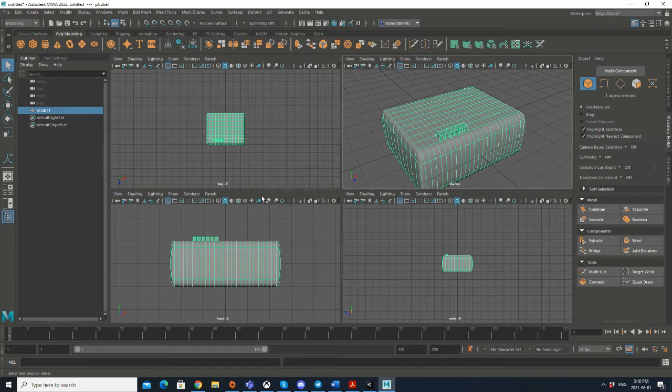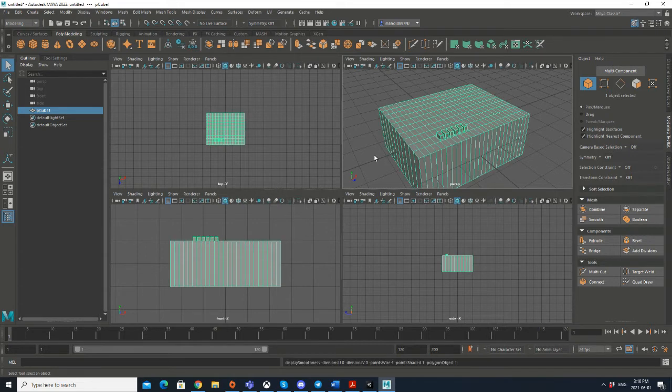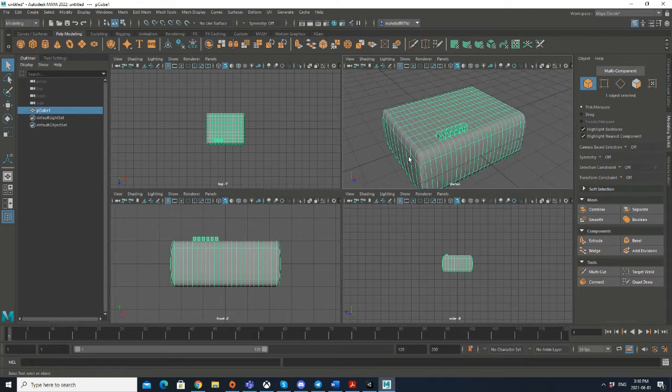Right. And yeah, how did you undo the smooth after you press 3? One. Okay, one goes to the normal mode, and three goes to the smooth one. Thanks. You're welcome. And continuing that question, if you want to go to the wireframe mode, you can use the 5, and for getting back, you can use the 5 to go to the shaded mode.